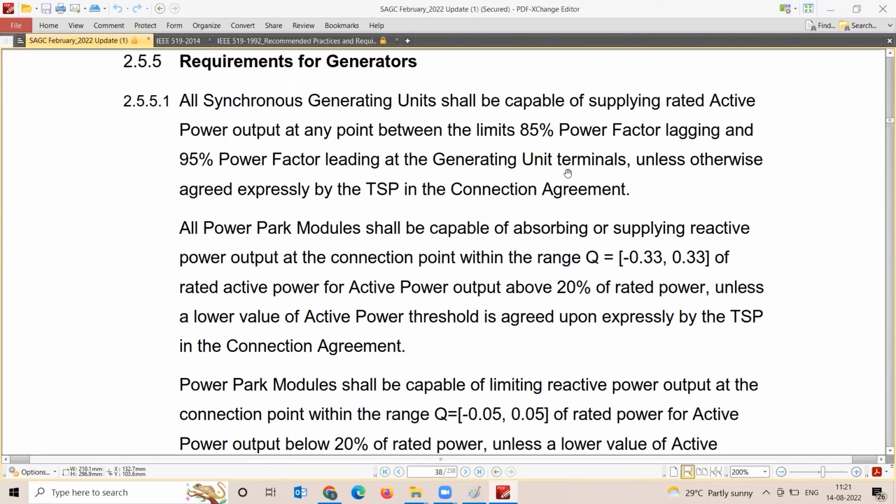For example, take the generator step-up transformer impedance for a 100 megawatt plant in India: the impedance will be in the range of about 10-12.5%. In Singapore, the impedance is like 25%. What does it mean? 25% of the MVA rating is lost as reactive power in the transformer itself, which means even if you're generating 60 MVAr, 60 minus 25, you will only be able to inject 35 MVAr to the grid at 66 kV in Singapore. That cannot be more because they limit the short circuit current you can inject into the 66 kV system. They will not allow more than 1 kiloamp at 66 kV. Then it is essential to go with that impedance, and obviously there will be reactive power losses. So here, at least, they are asking at terminals.